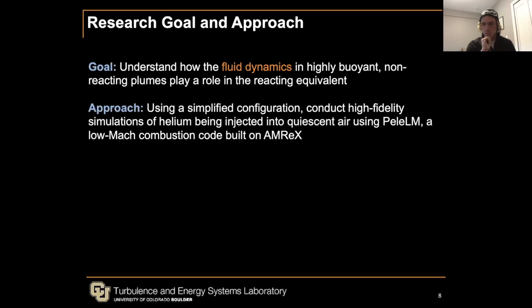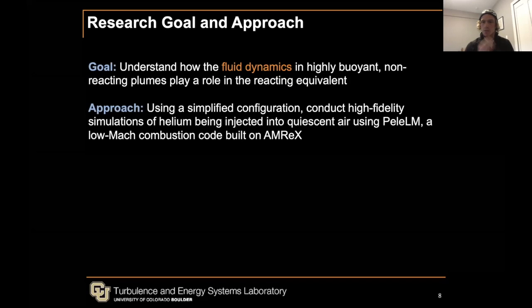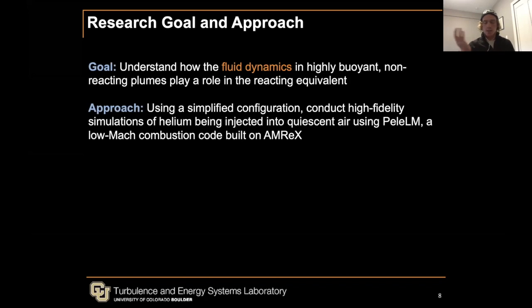To do so, we're looking at a very, very simplified configuration where we are injecting helium axisymmetrically into the bottom of the domain. We're doing so with high fidelity simulations. Whenever I say high fidelity simulations, it's like a coarse direct numerical simulation or an implicit LES simulation. There's no subgrid scale filter for these types of flows. And we're using PeleLM, which is a low Mach combustion code built on AMReX, and low Mach meaning that there's variable density, but the scales that we're looking at as far as the velocity goes are not compressible. So we don't need to resolve an acoustic time scale or anything.